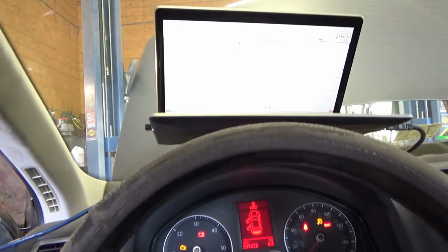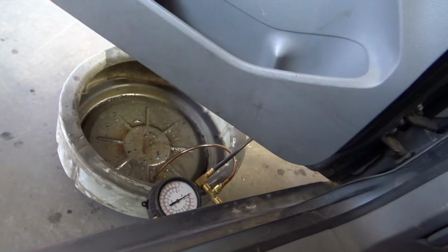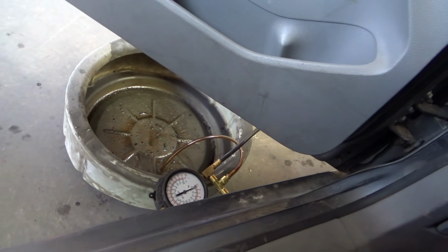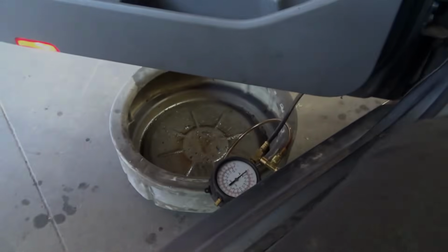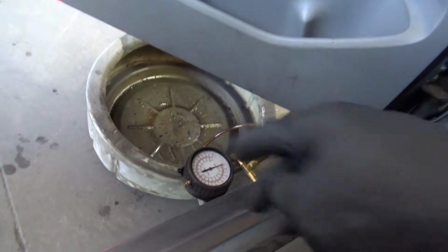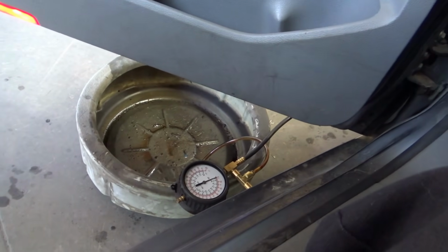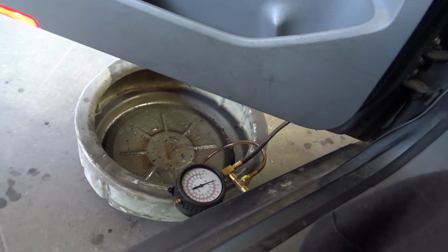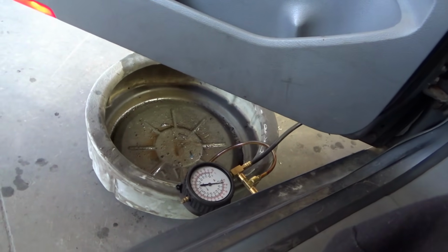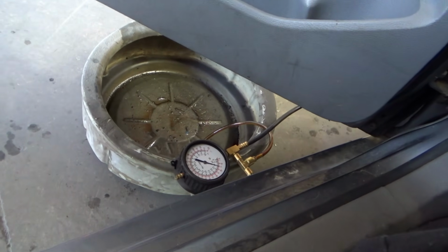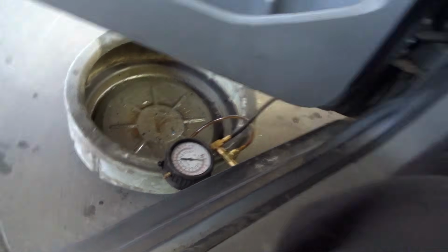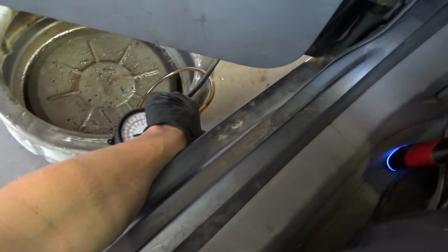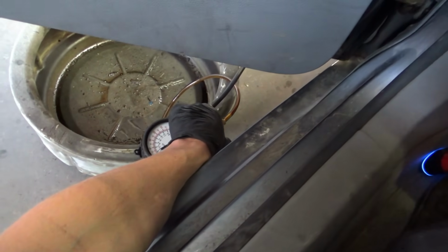Alright, we're all plumbed in with the new high pressure pump. Let's give it a whirl. Now this is going to be empty, so we're going to have to probably just crank it and hold that button down. Alright, so I got diesel coming out of there, so that should be bled out. 15 to 20 psi, our injector pulse is fine. Definitely have flow.